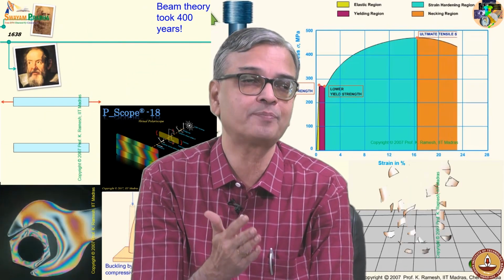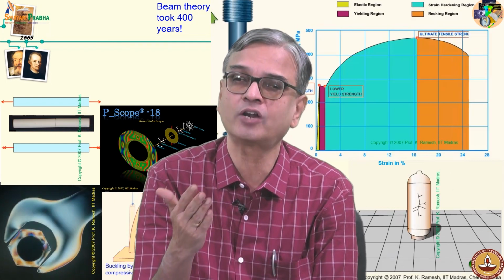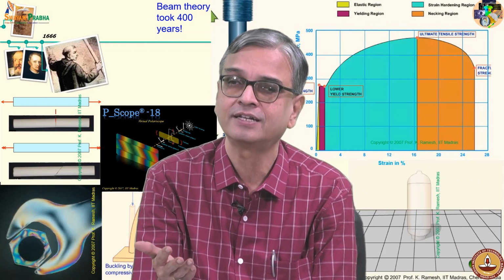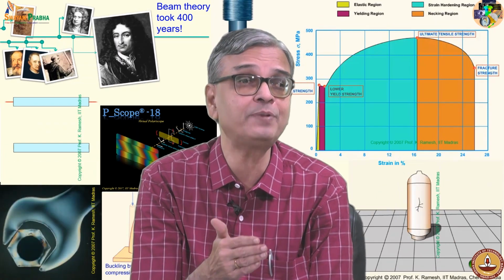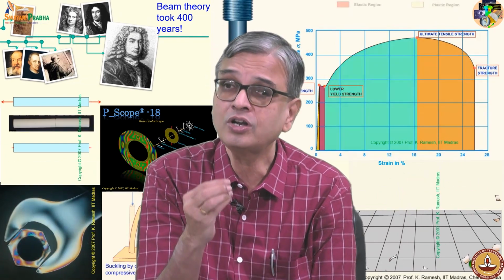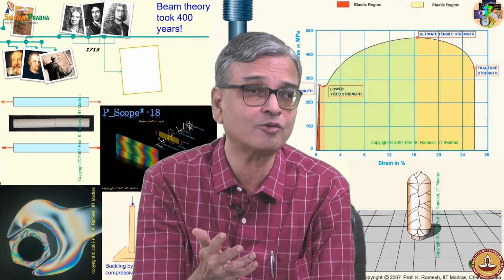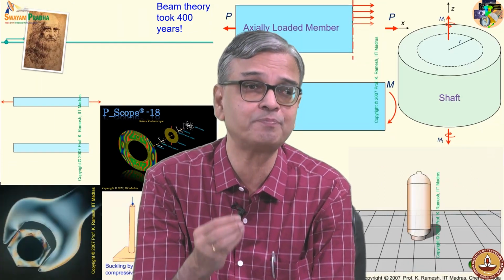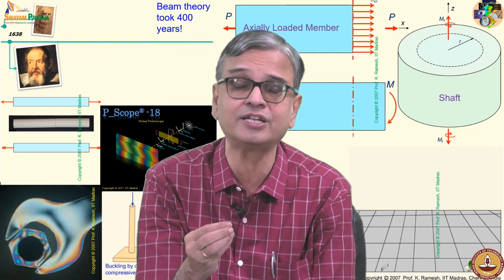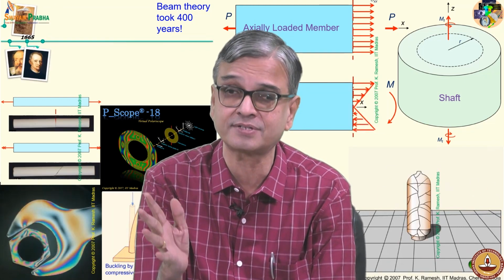If I have to analyze a plate with a circular hole, I should solve it by polar coordinates. Suppose I want to solve for an elliptical hole, you could not solve it with Cartesian or polar coordinates. So, in the early development of theory of elasticity, people did their PhDs to develop coordinate systems.